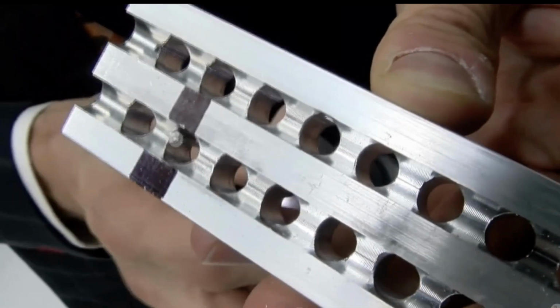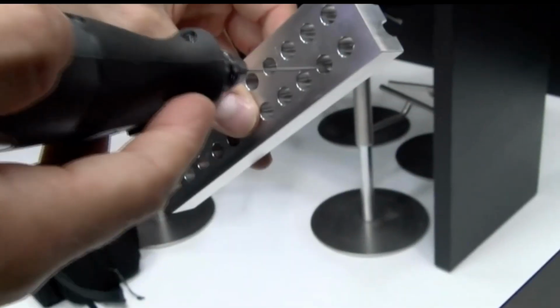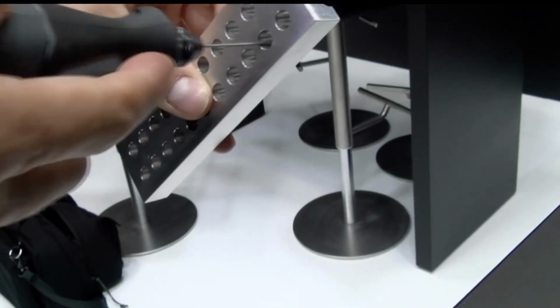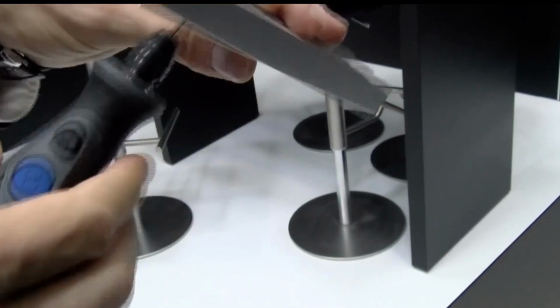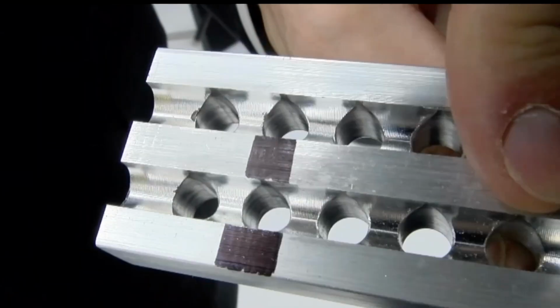So in this case, I can see what's happening, but if I'm the operator deburring this part in a real life setting, because I can't damage the wall in any way, I can really do this in a completely blind setting. I'm doing this entirely by feel. So that's the deburred hole, and no damage done to any other surfaces except where we actually need to remove the burr. Now we can see an example of this in a CNC setting.